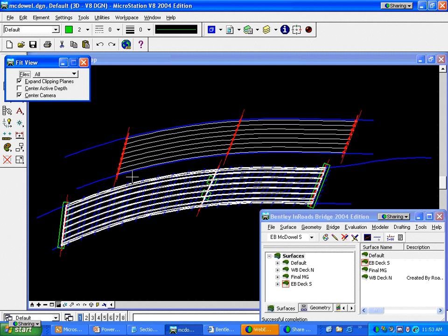And if I did that, I could still have used that, but I would have had to extend my abutment and bearing lines out past that center line because they have to cross the center line. It's just to help InRoads Bridge keep track of what all members are related to the center line.